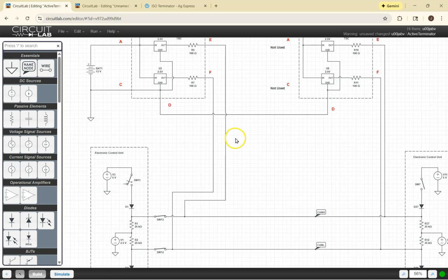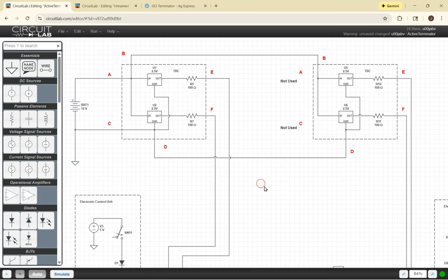If you remove both of the active terminators, I won't say this for the ISO network, the implement network, I've never tried it, but for sure for the machine network, if you remove both of the active terminators and put 120 ohm resistors between E and F of those connectors, this CAN bus works just fine. It is held at 2.5 volts.